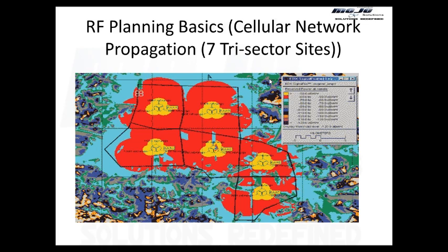Don't forget the dBm; the difference between dB and dBm is very important. And if you're standing in the green zone, it's between -70 and -80 dBm. Green zone is somewhere here, blue zone is here, then red and yellow zones. So that's the job of the propagation model.